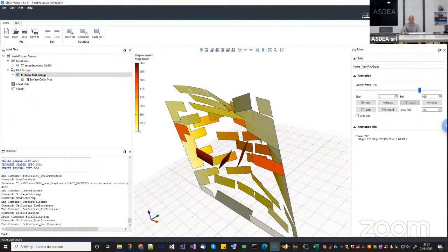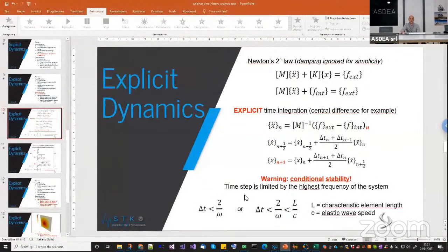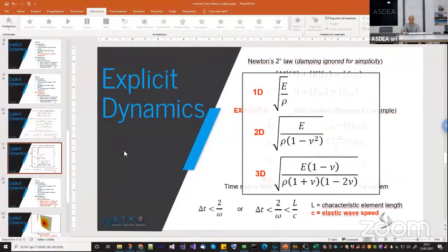Keep in mind that the equation that I gave for computing the time increment is just a first guess of the time step. Typically, you should use a time step which is much smaller than this one, because as you can see, this one depends on mass and elasticity. Now, mass remains the same because of conservation of mass. But the elasticity is not going to remain constant, because the Young's modulus can soon degrade. That's one of the reasons why I use element dilation. That's one of the techniques to avoid reducing the step too much.